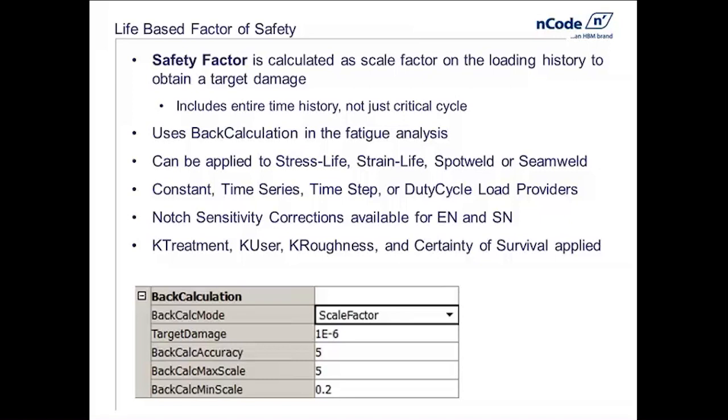Typically when we do a fatigue analysis, we bring in a loading, we specify a material, and a forward calculation would tell me the life at every node. The back calc goes in, is specified a damage and hence a life, and it iterates on the loading to come up with a scale factor that would basically give me that life. It's available in both high cycle and low cycle fatigue, stress life, strain life.